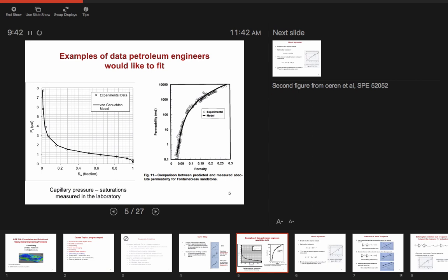Okay? So we measure properties of that type of displacement with a curve like this. So essentially, I start with saturation of water 1. I start pushing in oil or maybe gas, and I try to displace water, and then I go in a curve like this. At some point, I have a certain distribution of these cross sections in my rock where fluids are going through.